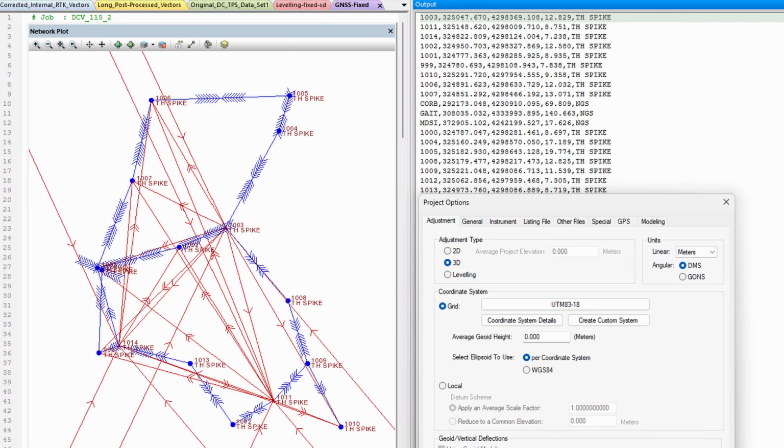What we ultimately want to do is to convert a set of grid coordinates to ground coordinates. For example, we want to convert a project site that we surveyed using GNSS that's in a mapping projection into a ground-based coordinate system. Why? Because we generally want to know the true ground distance between 2 points.